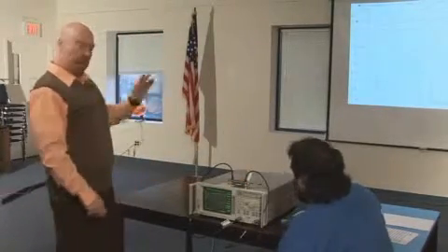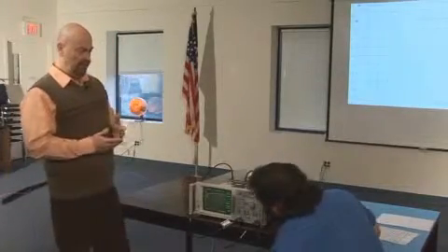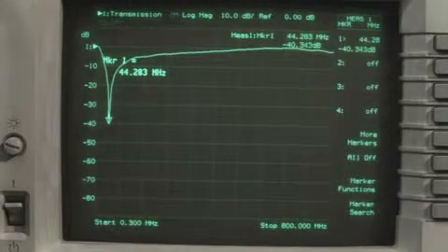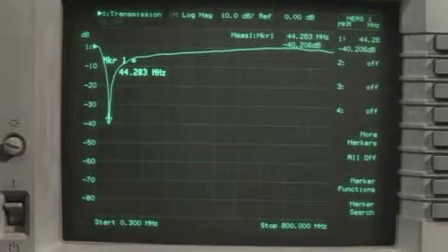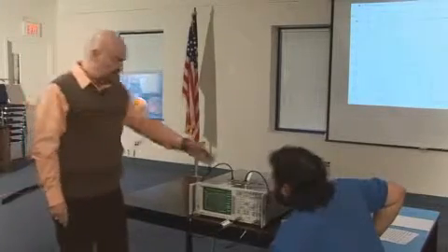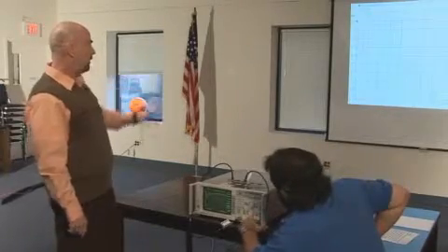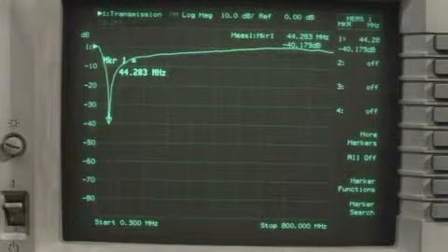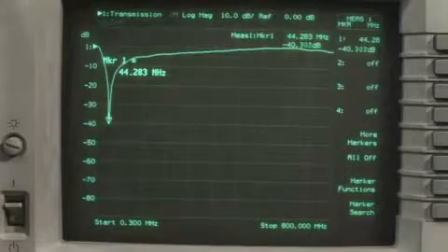there. And you know, most capacitors, when you put them in, they have a fixed point which is basically 1 over 2 pi fc, where f is frequency and c is capacitance, and in the filter world that's known as a notch. They have a very well-defined point. In this typical scenario, what we have is a capacitor across the line going to ground. So at that point, it has a low impedance at the bottom point of the notch. And it'll draw any signal at that frequency down to ground, and it will not feed further on down the line.